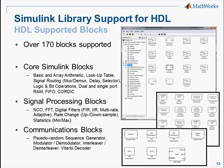Simulink HDL Coder now supports over 170 blocks from the core Simulink block set, as well as the DSP System Toolbox and the Communications System Toolbox. That means that you can reuse many of the algorithmic models you may already have and shorten the process of preparing models for HDL code generation. This slide highlights many of the supported Simulink blocks from these different block sets.